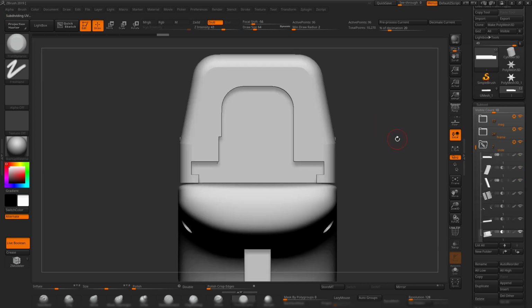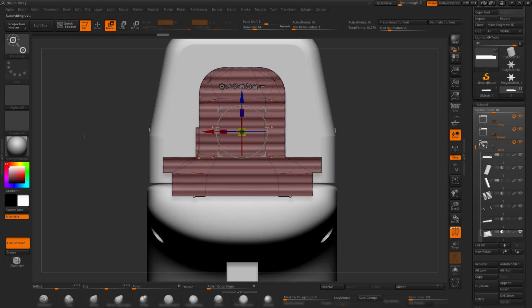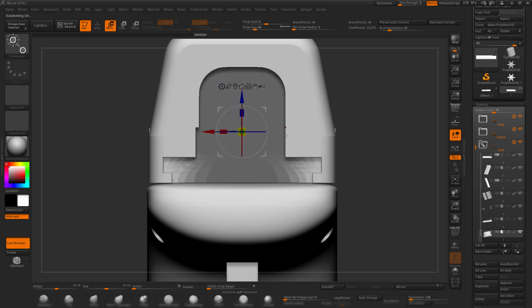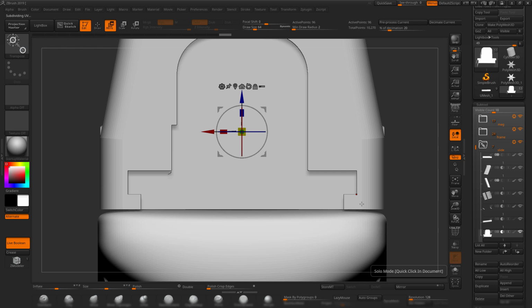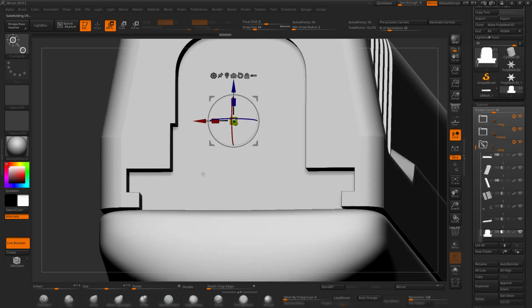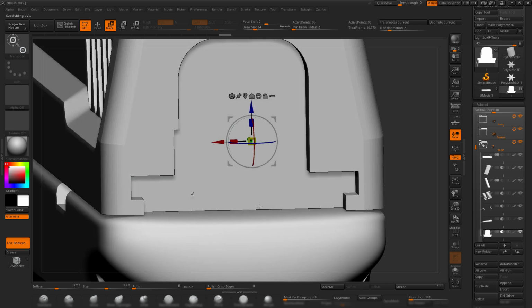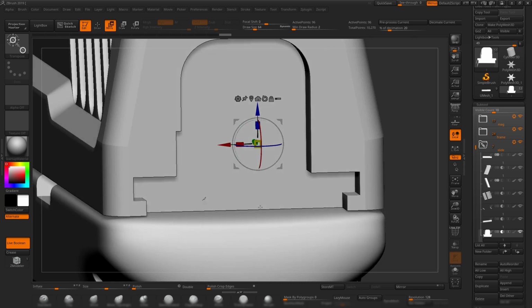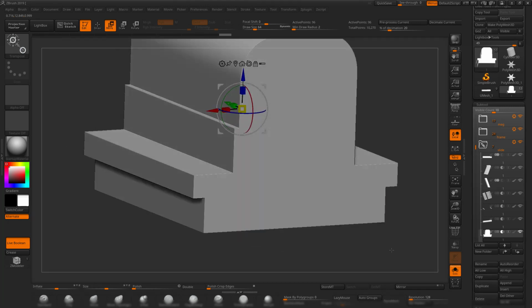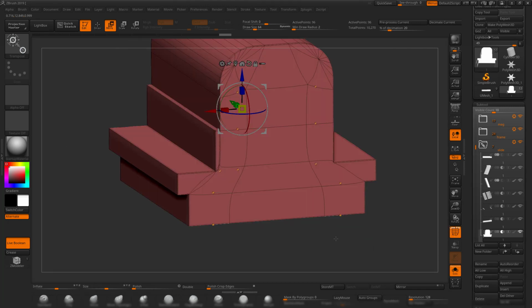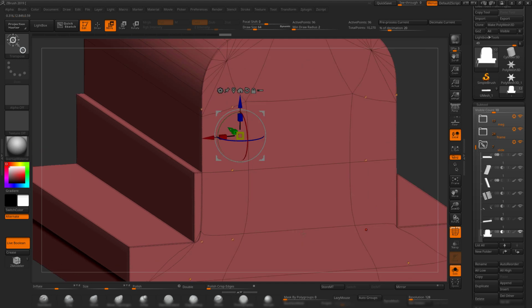As you can see right now, I'm not fitting that perfectly because I made this line. So select these and just scale them in just a bit like this. Yeah, this looks good. Still I can see some issues right there. This is nothing too special, not a problem. This is an issue caused by dividing this mesh, because as you can see right here, something weird is going on.